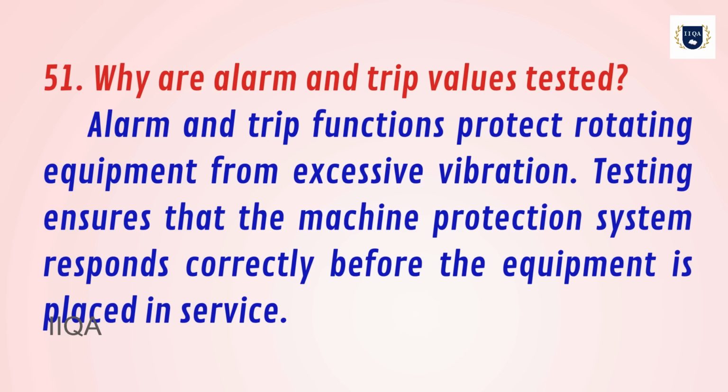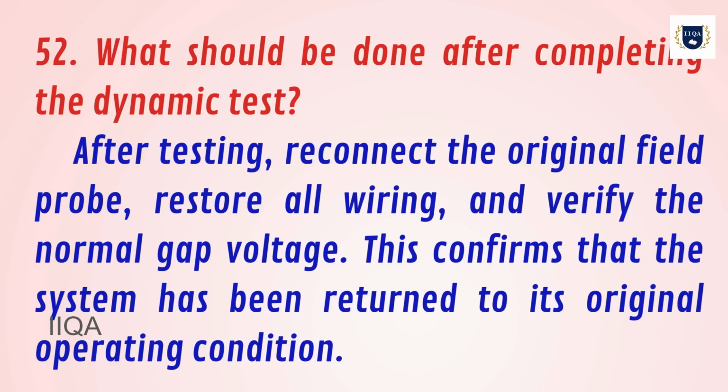51. Why are alarm and trip values tested? Alarm and trip functions protect rotating equipment from excessive vibration. Testing ensures that the machine protection system responds correctly before the equipment is placed in service.